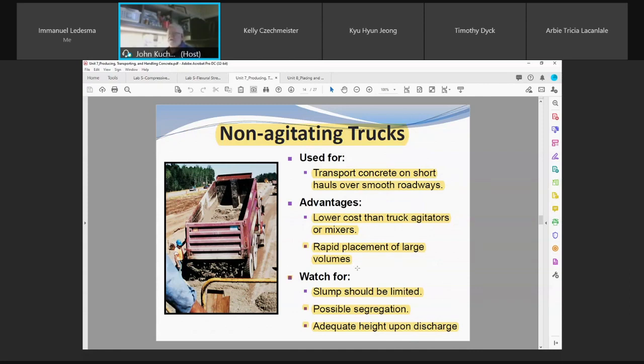And when you have large volume pours, it's a great way of moving 18 cubic meters of concrete versus 7 loads, 7 meters, 7 meters, 7 meters. Most ready-mix trucks, other than those big crane carriers that you see in Lafarge or even City Mix, they only have 2 or 3 semi-trailer revolving drum mixers. Most of them are about 7.5. Some of them are even 5.5 maximum cubic meter mixers versus a semi-trailer that can haul 18 cubic meters over a short distance. Okay, 3 times as fast.